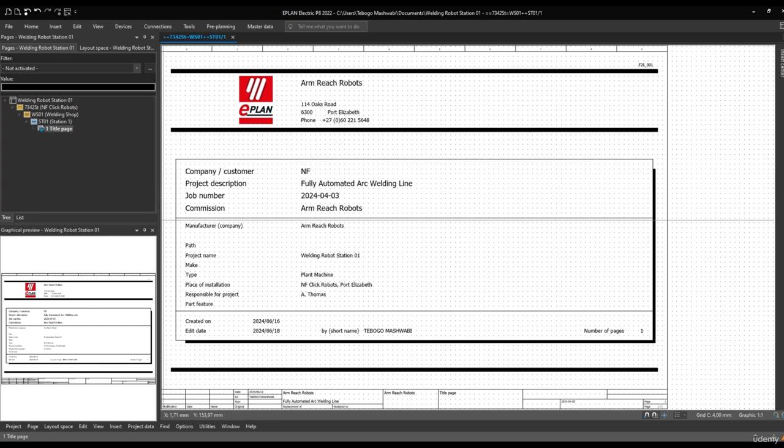So besides all the other information that you have in an Eplan project, an Eplan project contains individual page types. An example of a page type can be a schematic, a panel layout drawing, or a report. These page types can be separated from each other using structure identifiers. In the previous lecture, you have seen that we created some structures, like this one here: we have the functional assignment, the functional designation, and also the installation site. So you can separate your pages using structure identifiers.